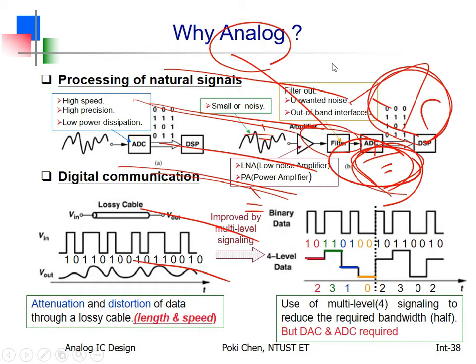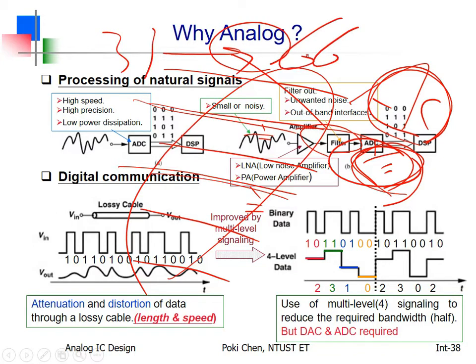Yeah, that is really troublesome because the number of wires needs to be doubled to make it from 33 to 66 megahertz. Nothing is free. You need to pay more money for that. And after 66 megahertz, nothing existed in our industry. If you would like to speed up the communication, sorry for that, you need to change your mind from parallel to serial communication.